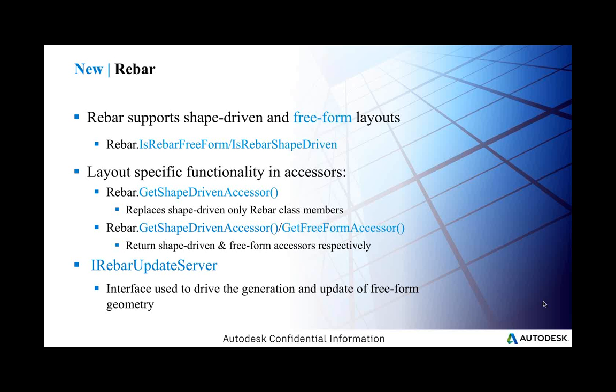There's a new interface, the IRebarUpdateServer, which can be used to automatically drive the generation and the update of freeform geometry with input from the underlying form. And if you remember at the beginning, I said that now the direct shape can host rebar.